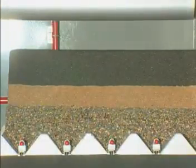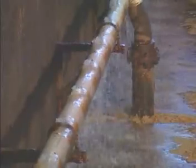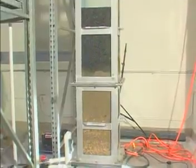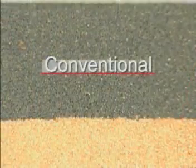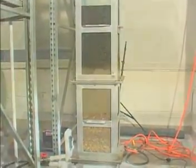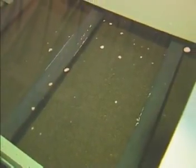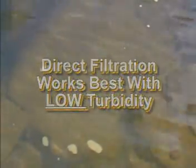Various filter types include multimedia filters, membrane filters, slow sand, and diatomaceous earth filters. The multimedia types are generally divided into two categories: conventional and direct. Conventional systems typically use the flocculation, sedimentation, and filtration sequence. The direct filters do not have the sedimentation stage.